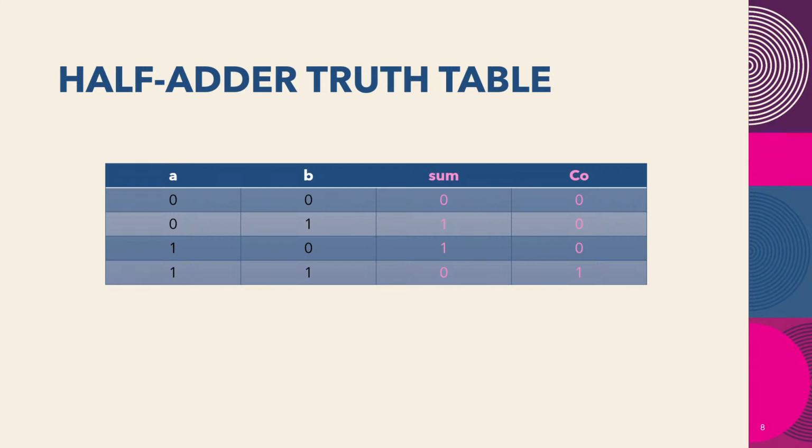If you look carefully at the inputs and the outputs, the outputs resemble exactly 2 well-known logic gates. Think about that for a moment. And if you don't know, try to figure out what are the logic gates that are showing up here. If you guessed that the logic gates were the exclusive OR gate and the AND gate, you would be right.